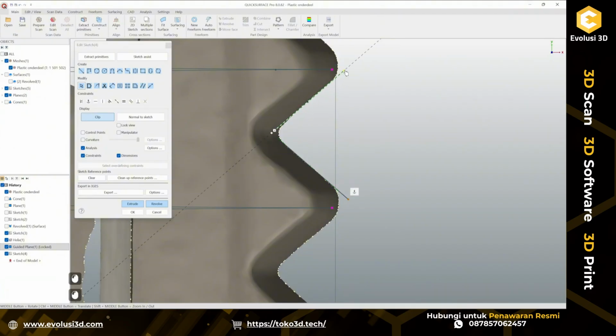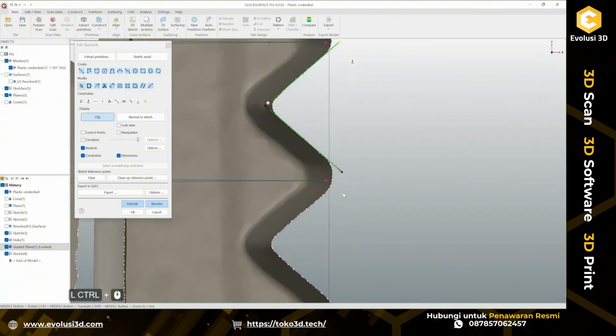So this is quite an important thing here, not to make a self-intersecting surface, because if we create a self-intersecting surface, we will have problems down the road, and this is a very well-known issue of the Parasolid kernel. It cannot handle self-intersecting surfaces, and this will be a big problem if you create self-intersection here, because the Parasolid kernel won't be able to create a good quality solid, and most likely you will end up with some errors.